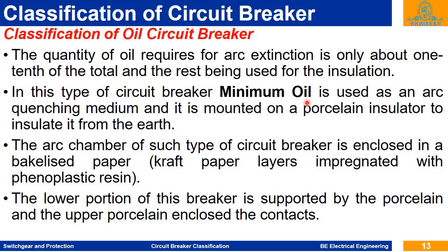After degradation of the oil, we need to filter it, so it costs very high. Sometimes if there is a blast in the circuit breaker, thousands of kilograms of oil are wasted. So that's why the bulk oil circuit breakers were modified, and next is the minimum oil circuit breaker.